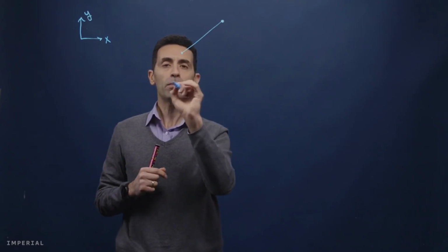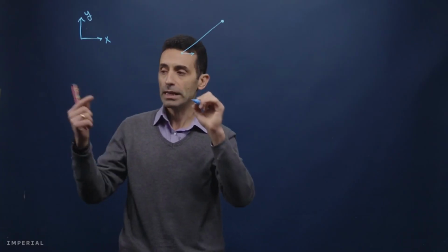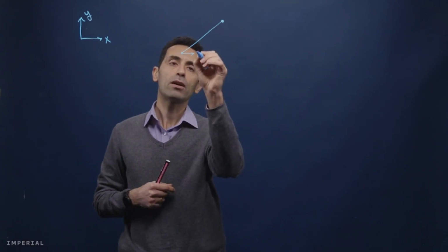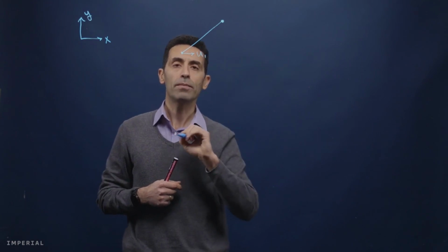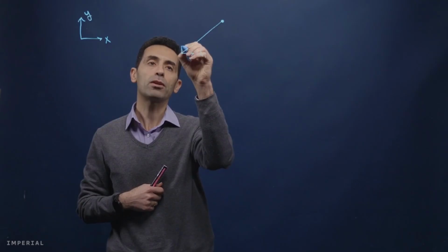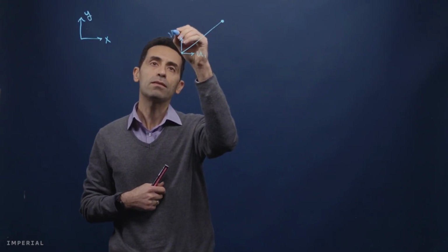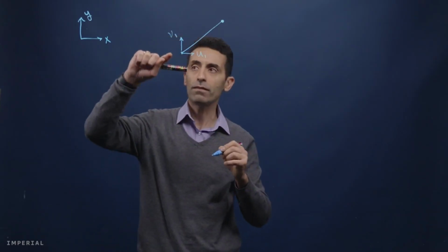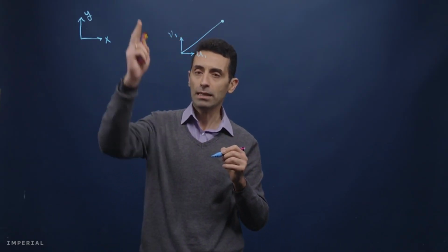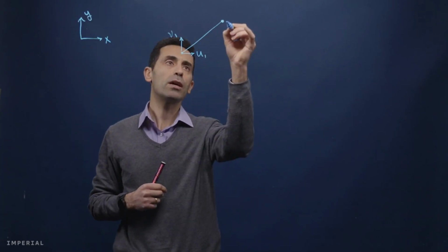In node number 1, now we have displacement in the x direction. So we call this U1. And we have displacement in the y direction. So this time I'm going to use a different convention. So this is V, that is defining displacement in the y direction, and V1 means displacement of node 1 in the y direction.